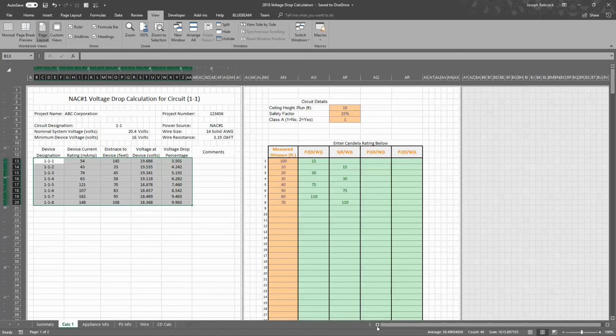There are other calculators out there that do have a little bit different numbers when they calculate them, but they do a lump sum calculation, which they just take the length of the circuit and then the current draw, and then they run the calculation for doing voltage drop across one lump sum over one distance.